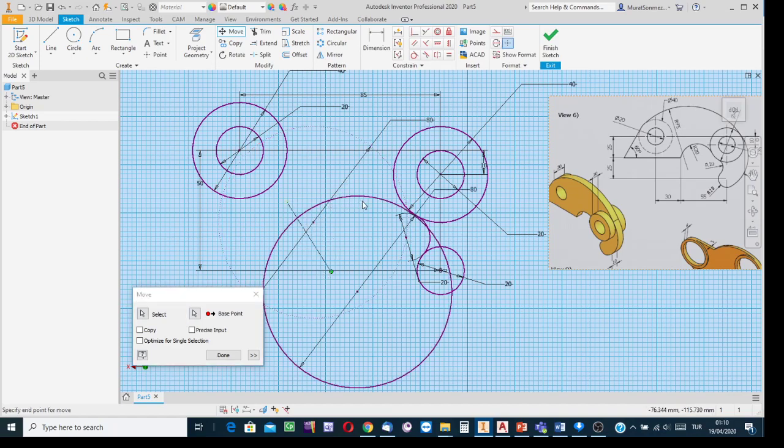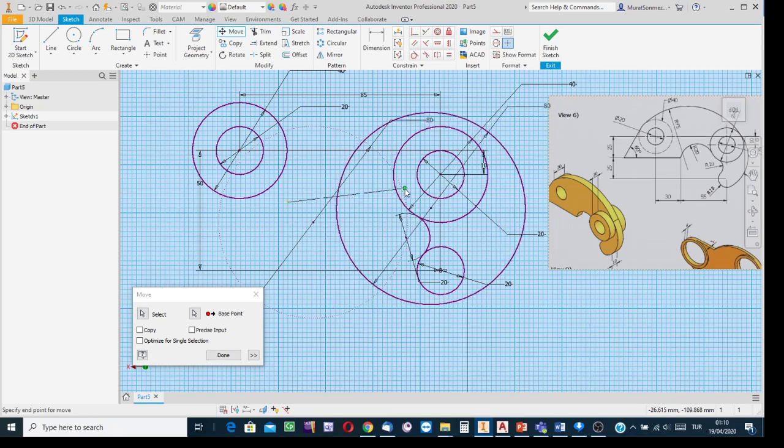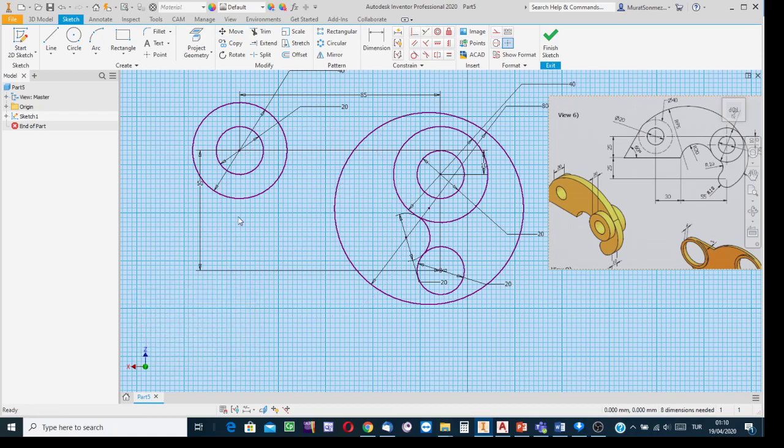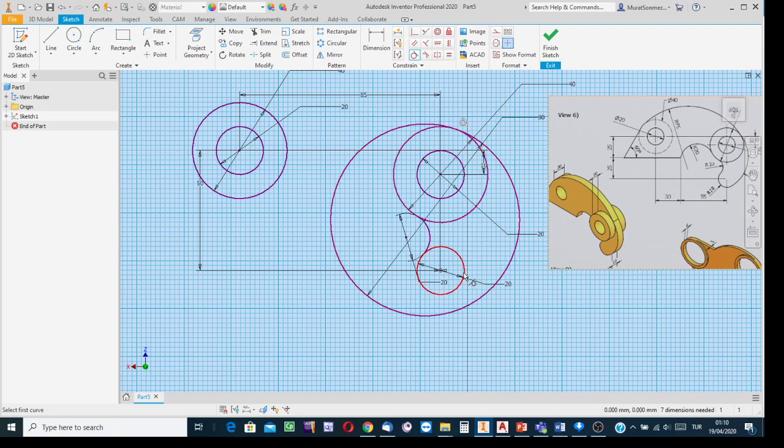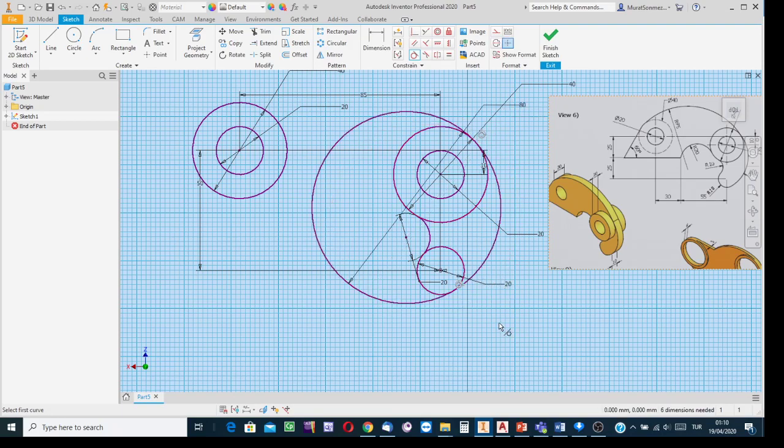Move the circle to the correct side, positioned such that the centers of the available circles are at the correct side. And then with a click, anchor it and click on the done button to finish the move process, and then apply the tangency constraint. Click on this, indicate this circle, indicate that these are tangent, indicate this, indicate the other tangent, and then trimming, yes, why not, apply.